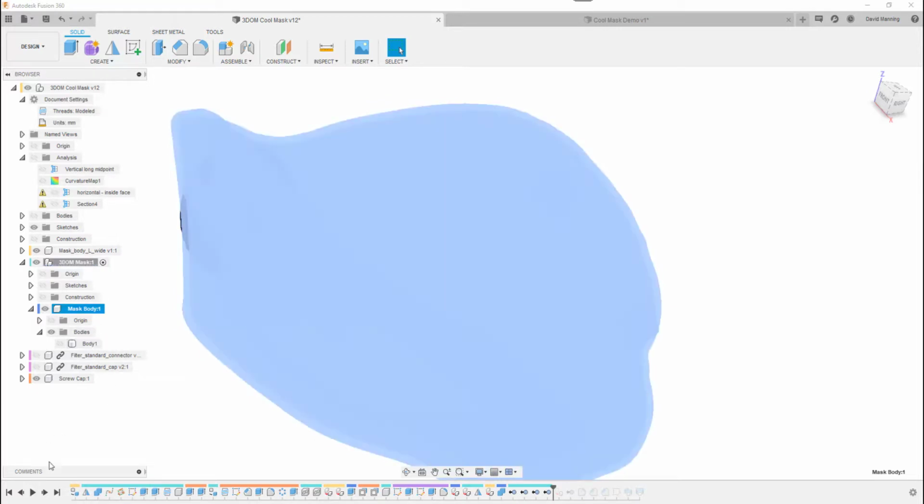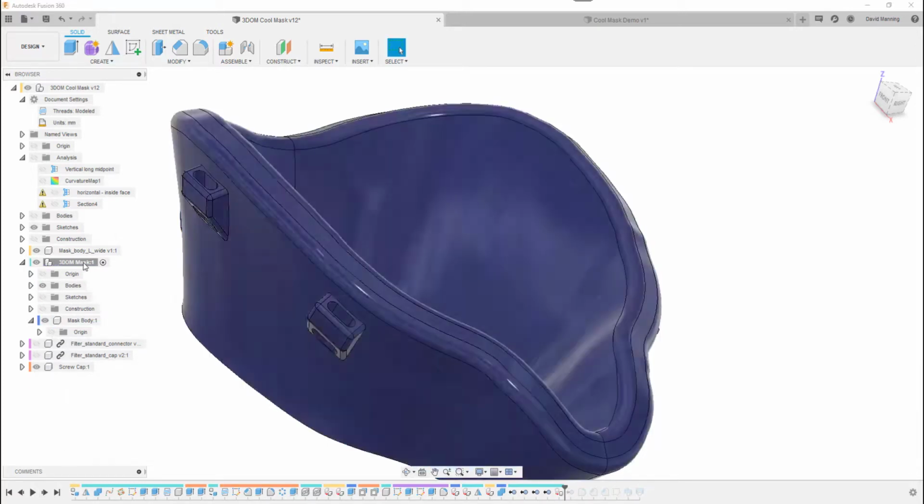So I decided to rectify that by moving it. You see this move command here, or cut and paste body, I simply dragged that up into that spot there and corrected that. So now that the body is under the assembly section, you see body 3, and the mask body has nothing. So I've then simply removed that again by right clicking and selecting the remove function.